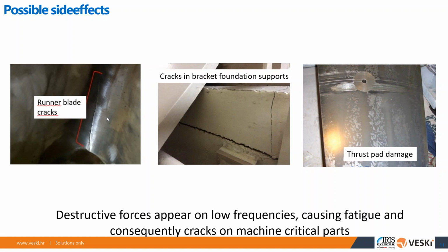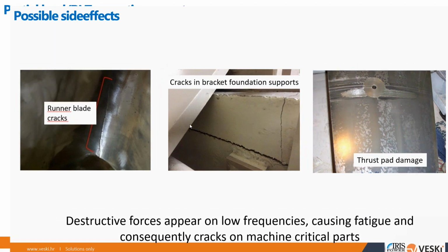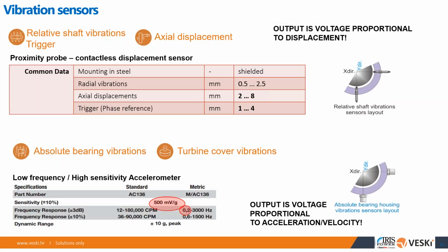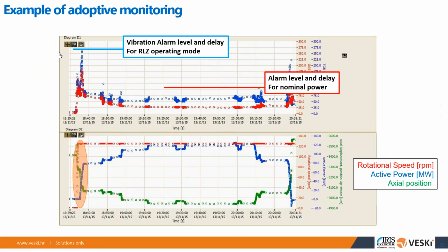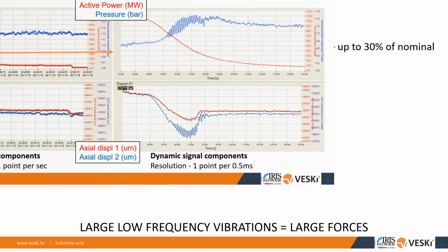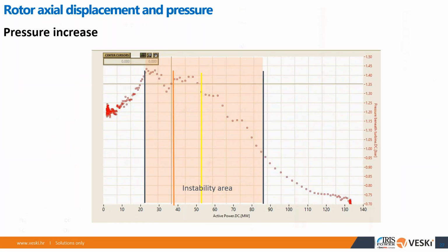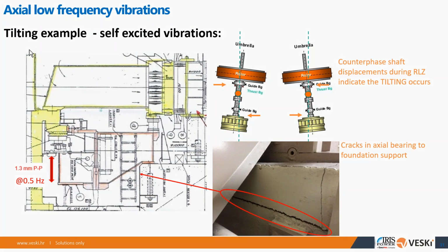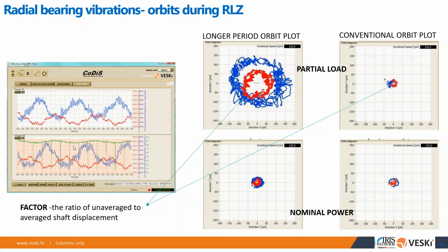The next question is, how well aligned was the unit you studied? I'm wondering what impact the overall alignment has on these vibrations you presented? If I'm correctly getting the question, the shaft alignment doesn't have to do anything with the low frequency vibrations. Shaft alignment would appear on 1x. Usually, if you have a dog leg or something, basically it's a slow roll vector, and it's related to machine frequency. Basically, we measure it on 1x.